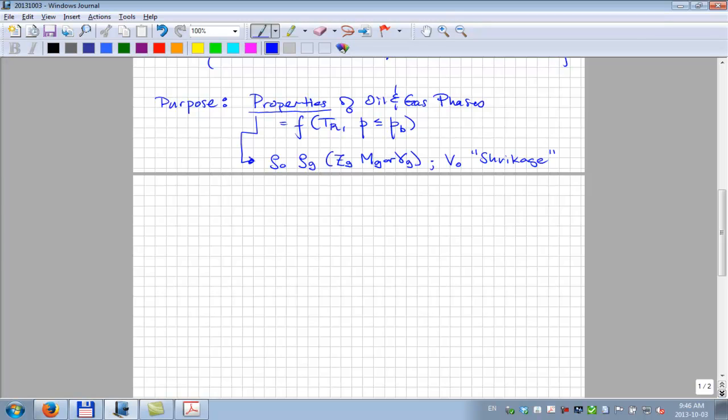Pamper me. Give me a little help. Why is the oil shrinking? Because some of the oil goes into gas phase. Yeah, because gas comes out of solution, the dissolution of gas. So the important question is, how much gas comes out of solution? Basically, how much volume of gas is released from the oil?